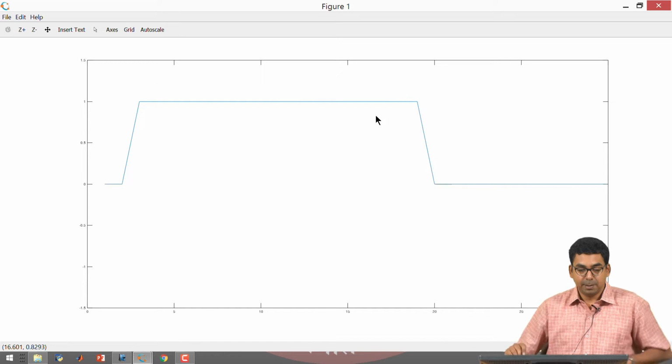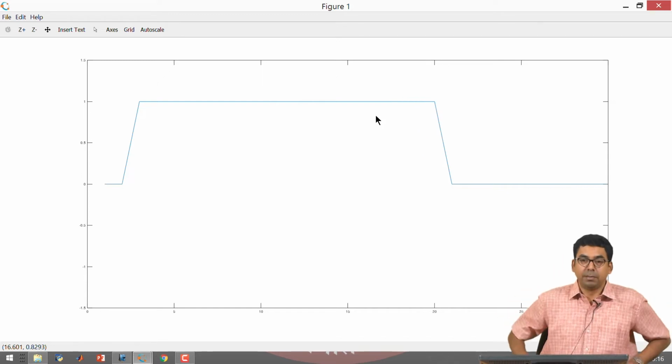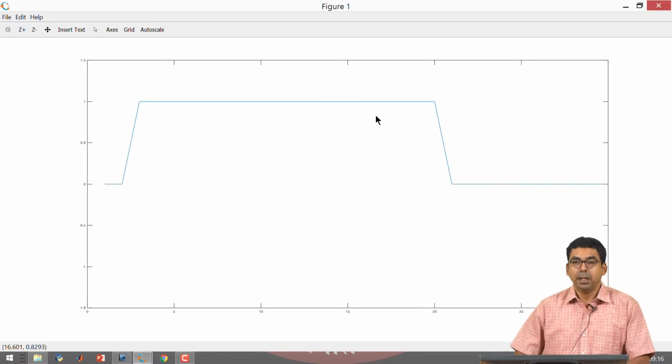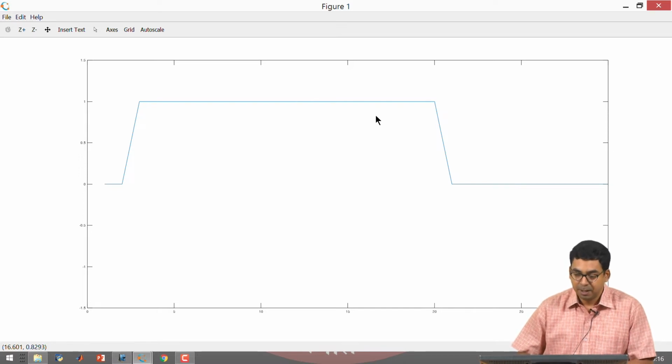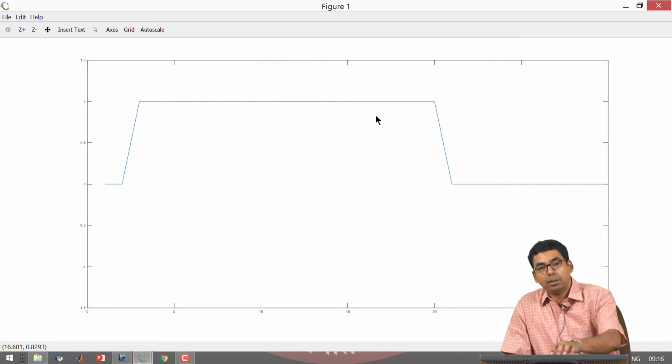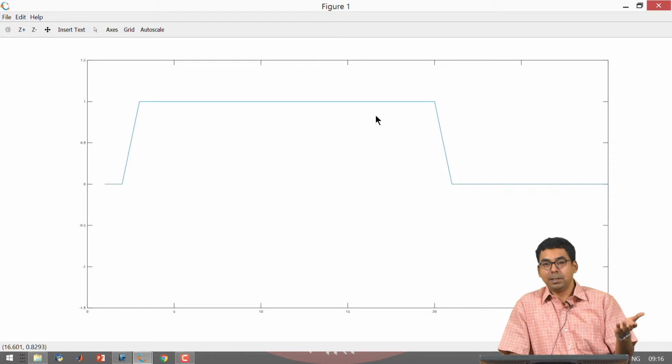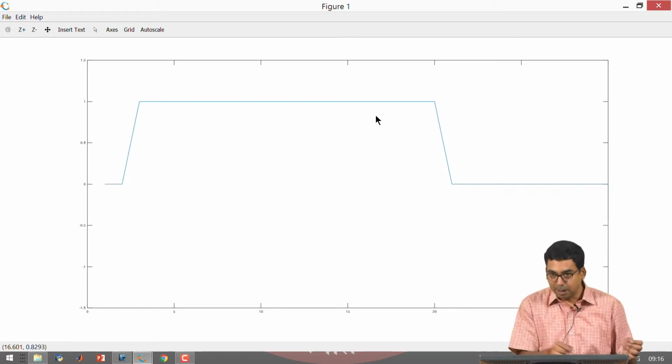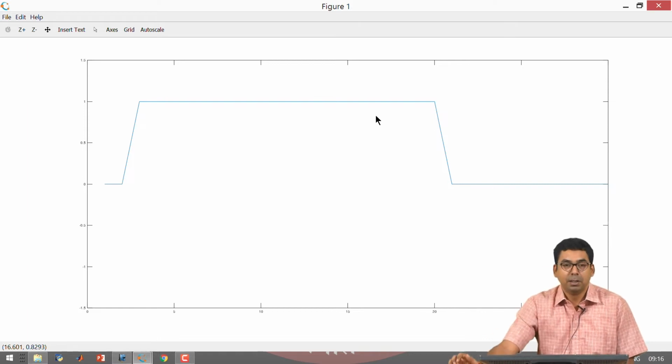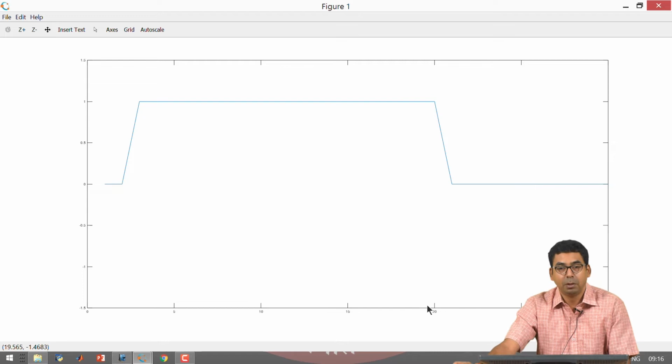So, here what is happening is that from the beginning, for all instants of time, position 2 is giving out a voltage of 1 volt. As time increases, you are just solving the wave equation, and the wave equation is telling you that the wave is traveling inside the transmission line. So, at 20 instants of time, it has a velocity of 1 cell per unit time, that is, it travels delta z distance in delta t time, because its velocity u is equal to 1. So, at some instant of time, it reaches the spatial location of 20.